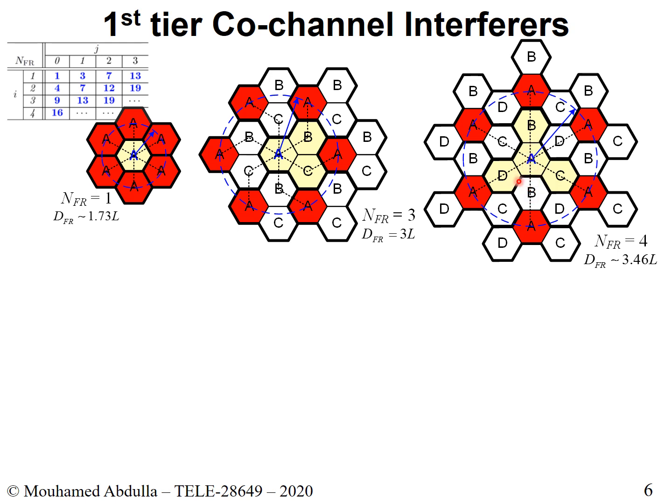So we have 4, and we look at our table. How did we get 4? Well, 4 is obtained when i is 2 and j is 0. So let's do that. i is 2, we move by 1, 2, it's here, and we don't move anything on the j, so we stay here. 1, 2 here, 1, 2 here, and so on and so forth. So here, the trace to obtain your co-channel is just a straight line, because your j is 0. Okay, so that's that.